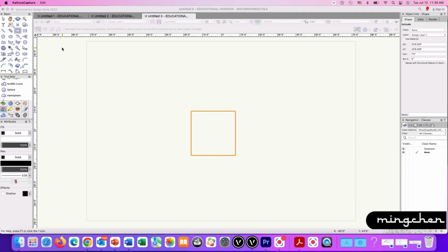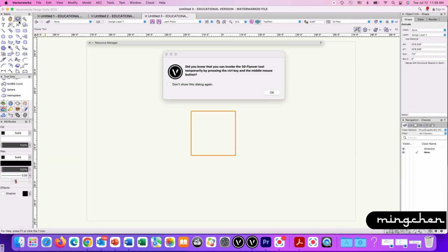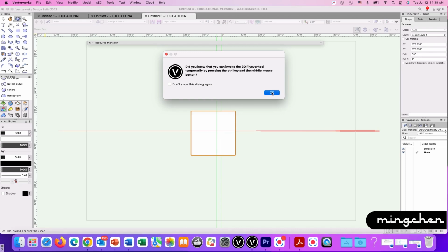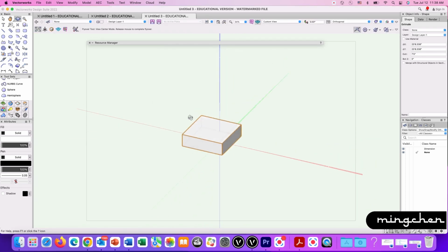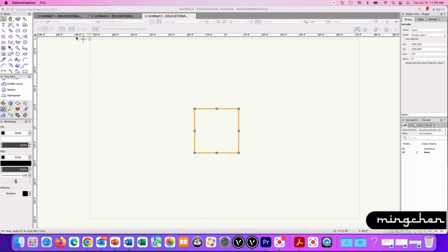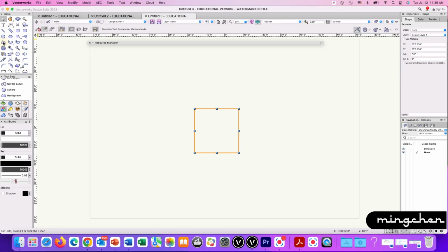As an alternative, you can also use the flyover tool located on the basic palette to drag the object to a customized viewing direction and angle. Note, you can also switch views by invoking projection view tools and walkthrough tools. These will be covered in the later videos.